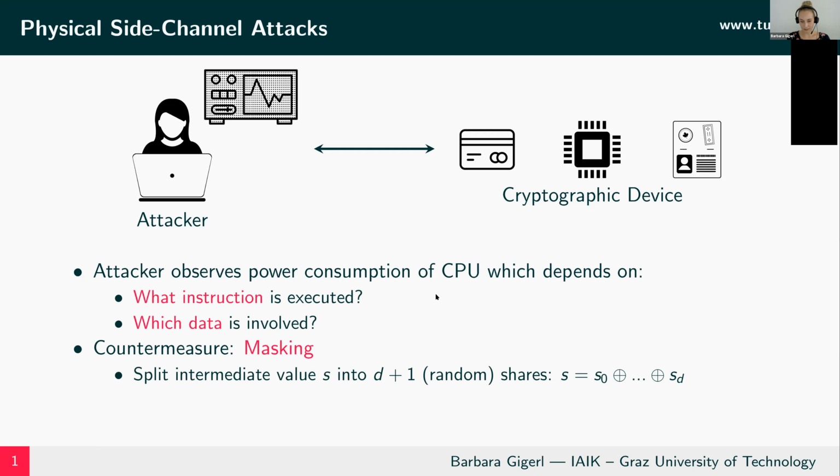Okay, so those masking verification tools so far exist either for masked hardware circuits. For example, here you have Rebecca and mask-verif as one of the first tools. Basically, these tools check for a given masked circuit whether there exists a gate which combines two shares. These checks are done in the so-called classical probing model, which defines the abilities of an attacker.